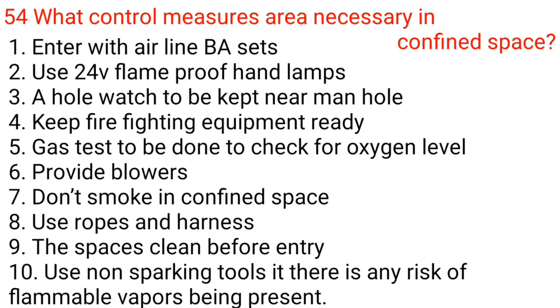8. Use ropes and harness. 9. Ensure the space is clean before entry. 10. Use non-sparking tools if there is any risk of flammable vapors being present.